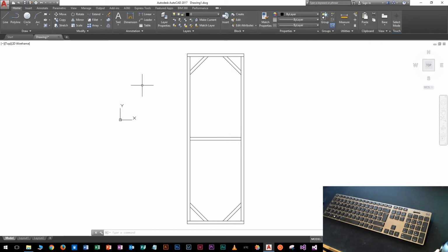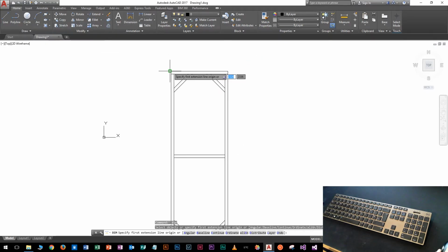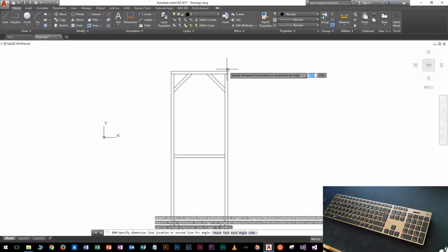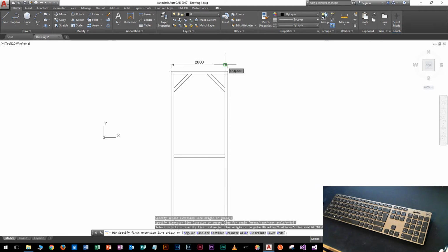And then we can just use this dimension button to pick up a dimension and draw it on. Now we can draw this on in two ways. We can click on the one end and click on the other, and then do a third click up, or we can click on the dimension and actually hover over the lines, and you can see that it automatically puts those in.